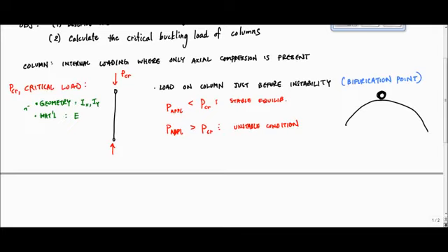I changed the length, and what did I do? I increased the buckling load. So now length. Okay, so geometry is I. Let's also include the length. And then what about how I hold it? What if I hold it by my little itty bitty fingers like this, like a pin support, versus let me use my fist and hold it tight. Obviously which way will be stronger, if I just use my fingers or if I use my hands? My hands, like a fixed support.